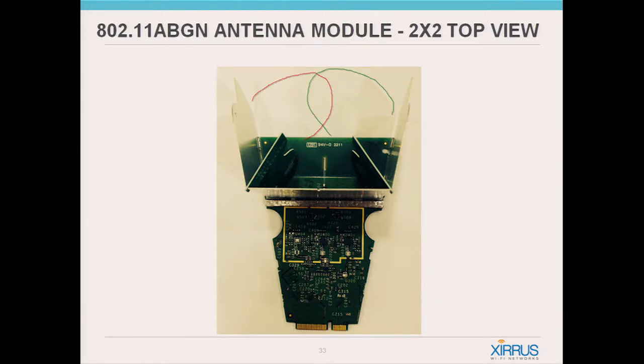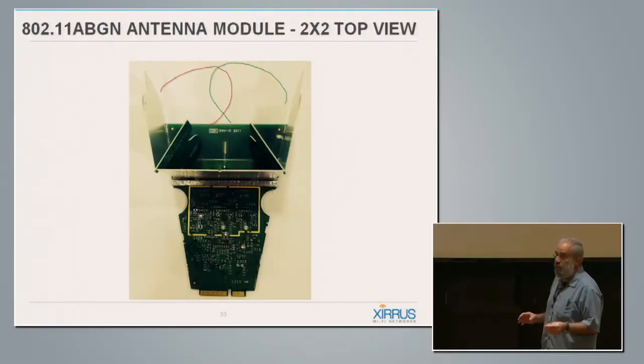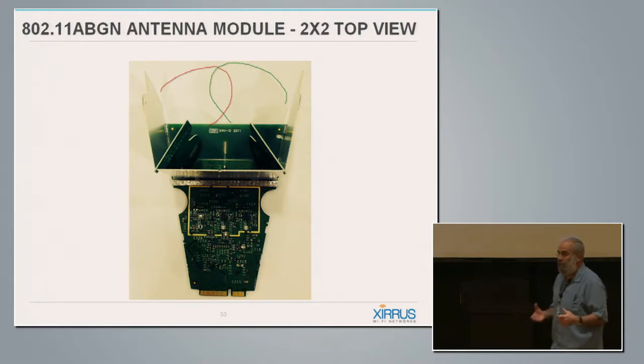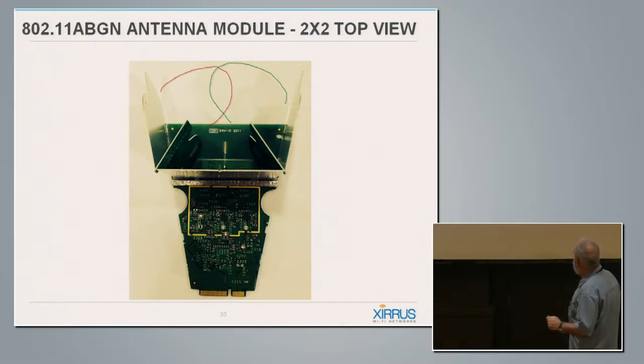So what I'm doing is, when we have multiple channels in a MIMO situation, it's not going to be efficient to have all the antennas pointed in one direction. So rather I'm creating more like a space diversity. So when this antenna is shooting energy more in that direction, this antenna is shooting more energy in that direction, and the beam width is about 60 degrees. So it's kind of directional, not that directional. But overall, I'm getting two beams that overlap each other enough.